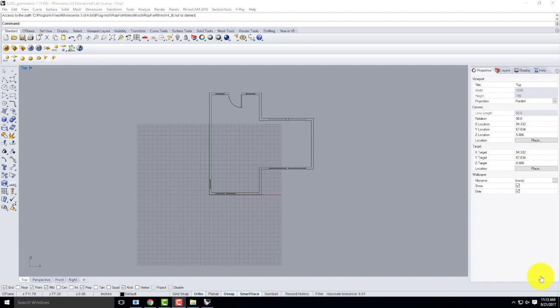And I'm not under the illusion that we're going to spend a bunch of time drawing fancy elevations or figure out roof pitches or whatever. That part doesn't matter. Essentially, we're drawing what the wall looks like. So when we refer to a Rhino file and we refer to elevations, generally straight up the y-axis is north. Generally straight down would be south, and then we have east and west to either side. So in this case, if I'm talking about drawing the south elevation, which is what we're going to start on, it's what we would see if we were standing right here at the bottom looking this way. That's the elevation that I'm talking about. And by elevation, I just mean the side view of this particular building. And so we're going to go ahead and draw it.